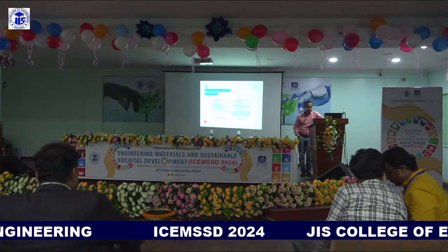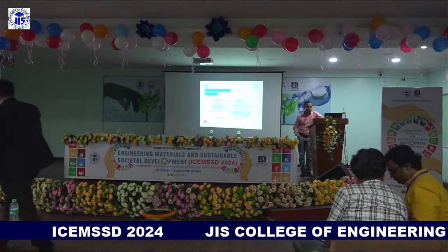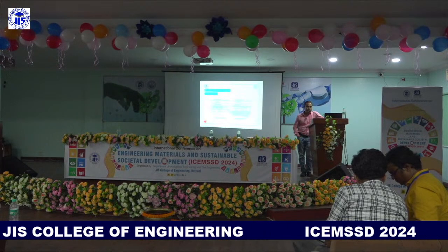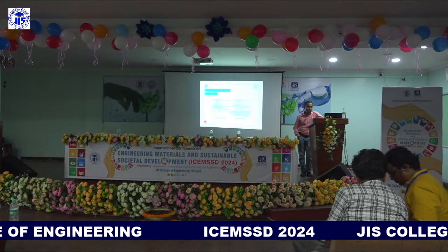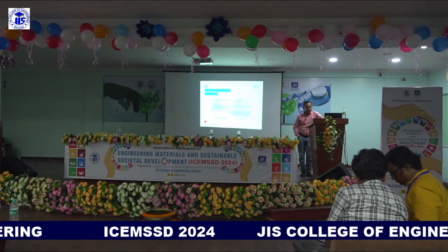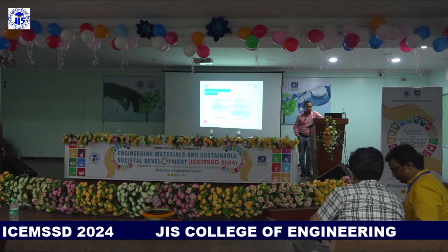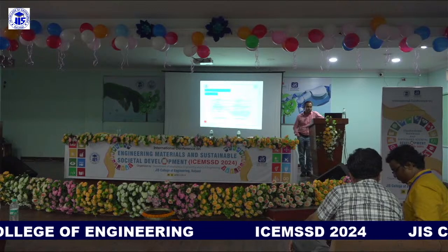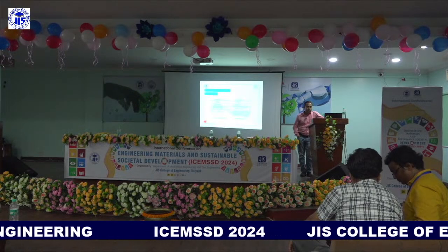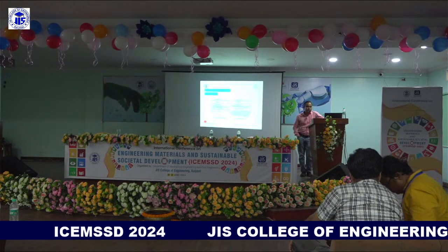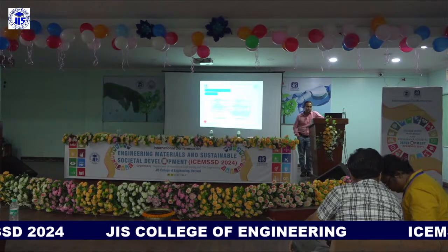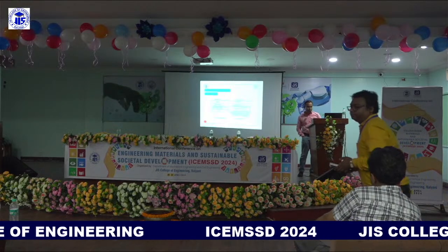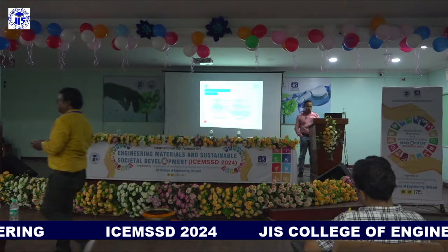Above this, the layer is called the interfacial sublayer or form sublayer, where the effect of bed roughness is there, and the effect of the viscosity of water also takes place. Above this, the velocity profile follows the logarithmic law, so it is called the logarithmic layer. Above this is the outer layer, where the flow is generally controlled by turbulence, and this is the fully turbulent zone. We are mainly working with this zone only, the outer layer and the lower layer.